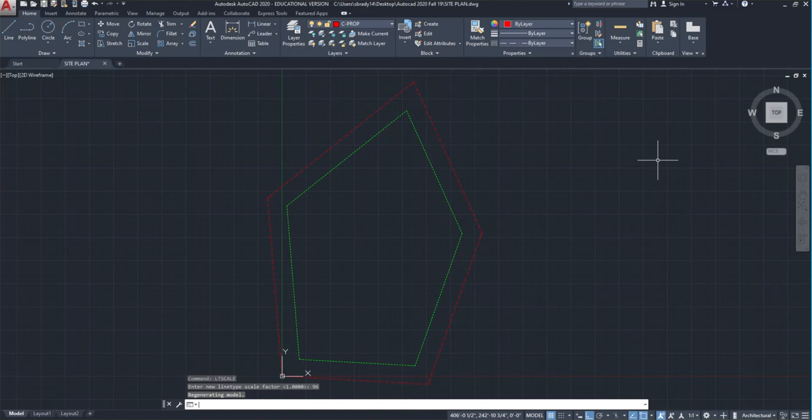And you're like, wait a minute, it's half the plot scale factor. I type that in, I hit enter, it looks good. I can't tell you why sometimes it works and sometimes it doesn't. There's just so many things going on in AutoCAD. But my best practice for LT scale, if you're not getting dashed lines, start with half the scale factor and work in half increments down until it looks right. Let me just say that.